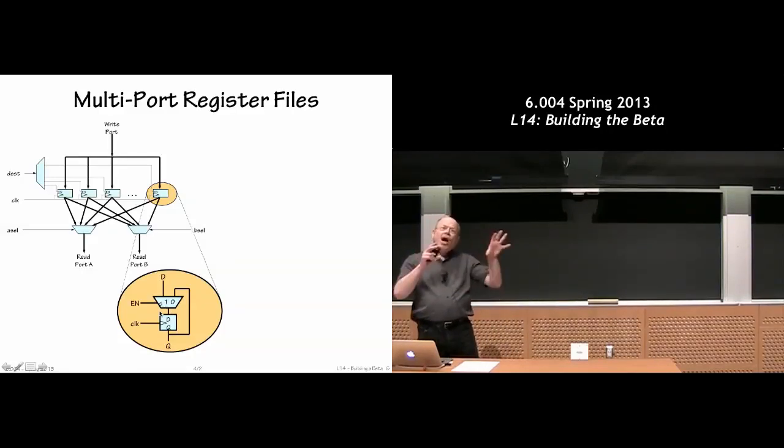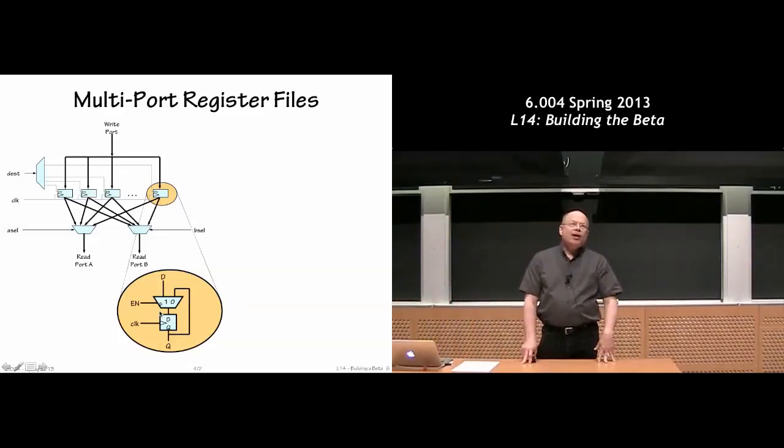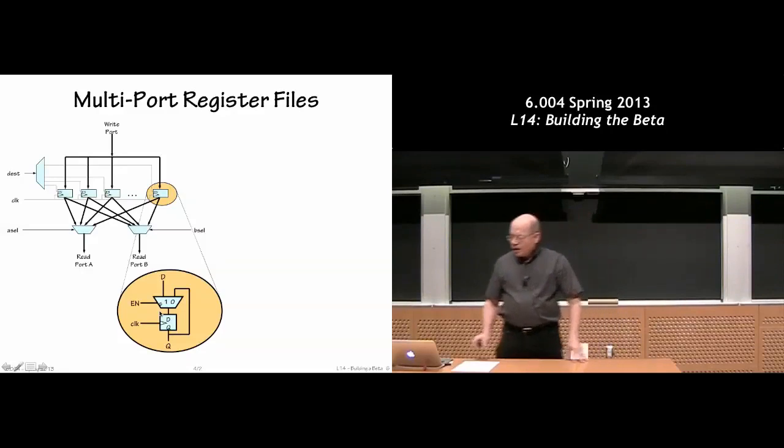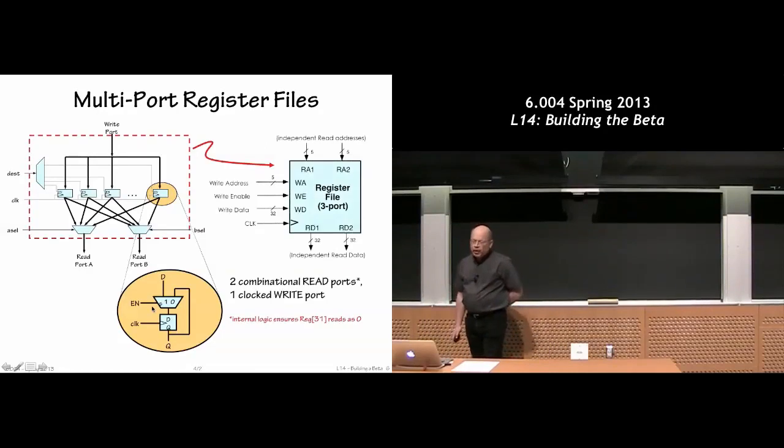The trouble with using logic to do clock gating is that any sort of little glitch in the logic might produce an accidental clock edge, and the register might clock accidentally. As you change the values on the enable signal, you don't want all of a sudden a clock edge to be produced. So this way, the clock goes directly to the registers, and we're using the enable signal to control what the registers will load.